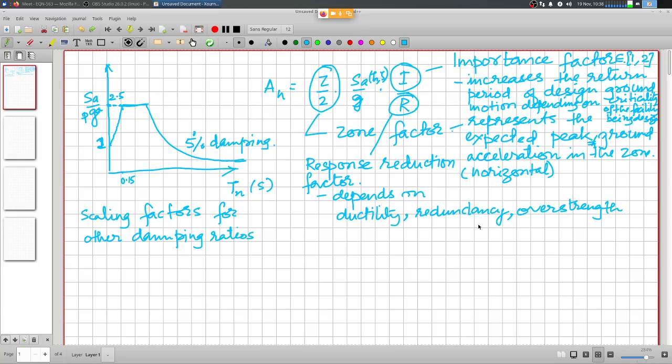So obviously whatever bar you might be using with a rating of 250 MPa or 415 MPa, the actual yield strength might be much higher than 415 or 250. What is that actual strength? You don't know. So typically what is done is one batch of steel reinforcing bar is tested up to, let's say, 550 MPa, and if it does not fail at 550 MPa, it is taken as having passed the 415 MPa grade, and it is pushed out with the label of 415 MPa.